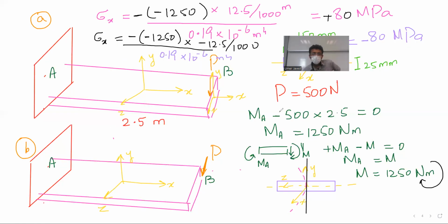If you bend like this, hang on. So if I'm putting a load like this, that surface will be in compression, this one tension. This surface will be like this in compression. So for a value of positive Z, I need to give a negative answer. Yeah, for positive Z direction.